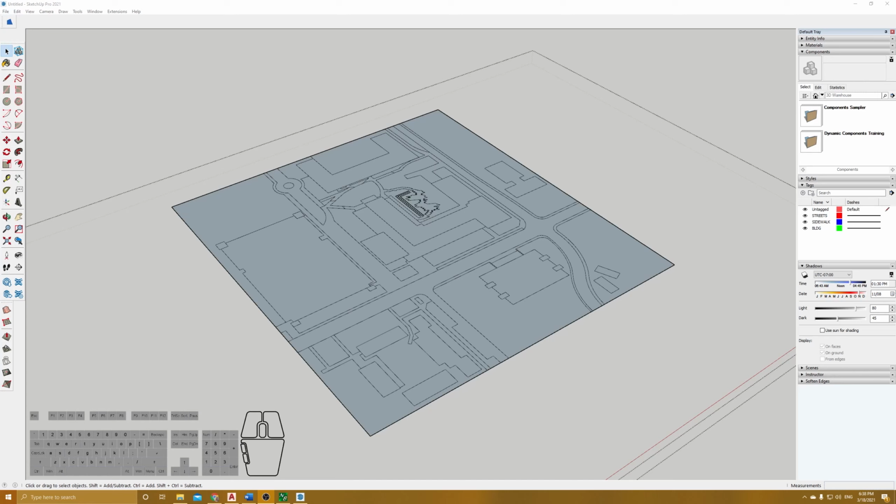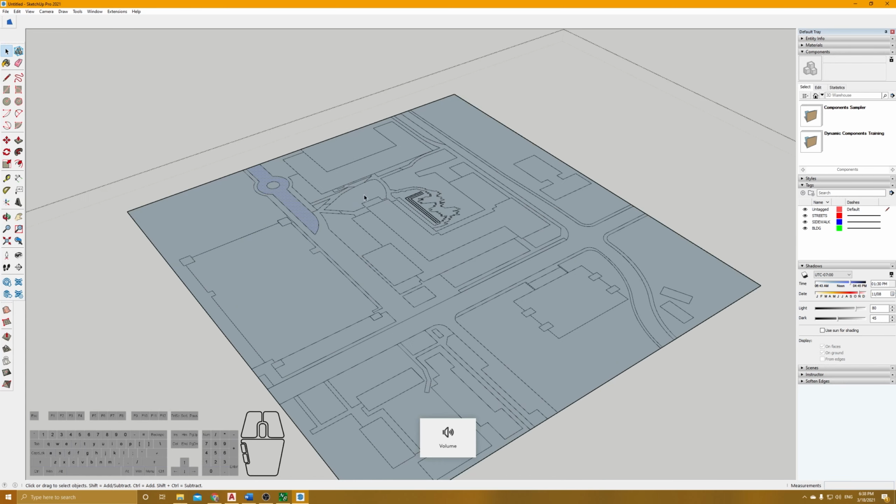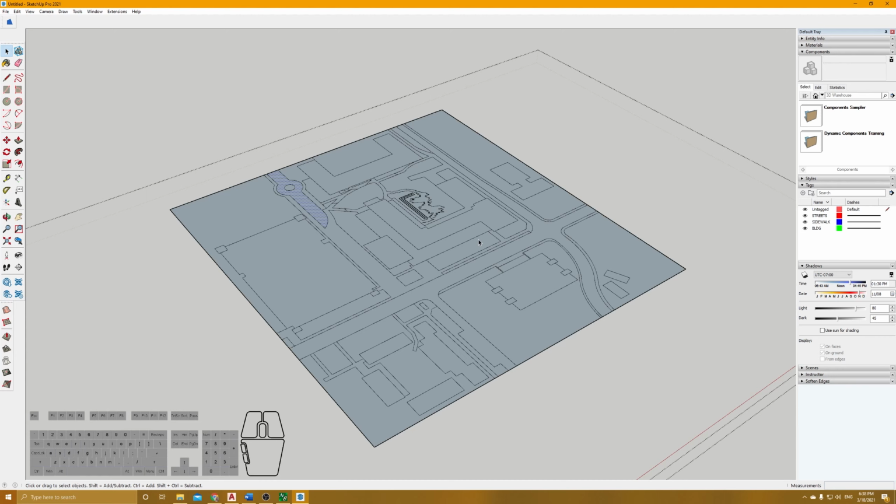All right, now that I've gone through my model and repaired some of the geometries, we can see that we have individual faces for each different geometry. So just a note that when you bring AutoCAD line work into SketchUp and start to make faces on it, sometimes it just doesn't always work, and you do have to have a careful eye to watch out for geometries that may be a little too long or don't actually connect to the next line all the way. So there might be a gap in some of the geometries. A way to fix this is just make sure that you're really accurately drawing in AutoCAD and that you have a good eye when you come into SketchUp to fix these minor issues that may have come along with the import of the file itself.